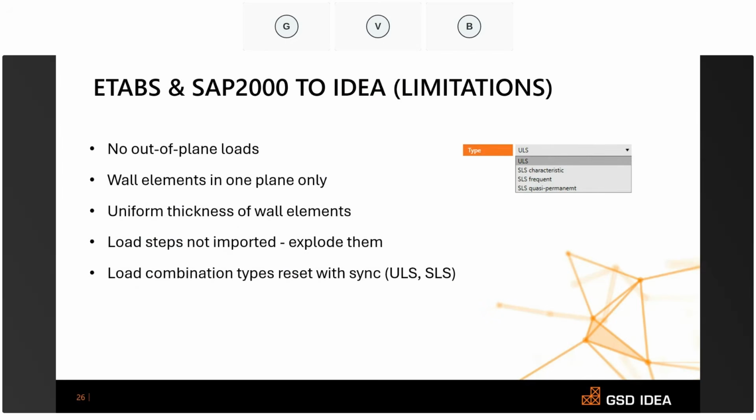There's also one more point to take note of. When you synchronize, the ULS and SLS combination types reset, so you will need to reassign them manually again. And that's all with the BIM links as well.